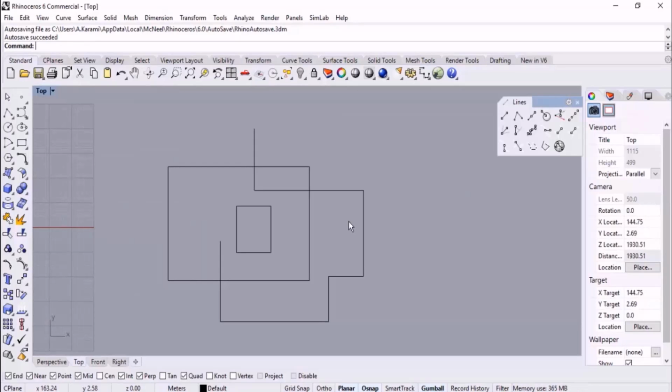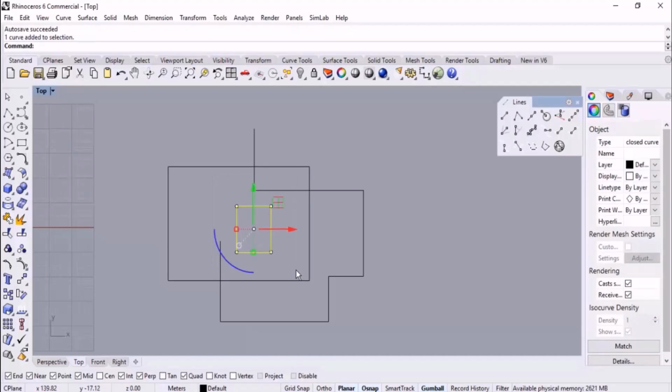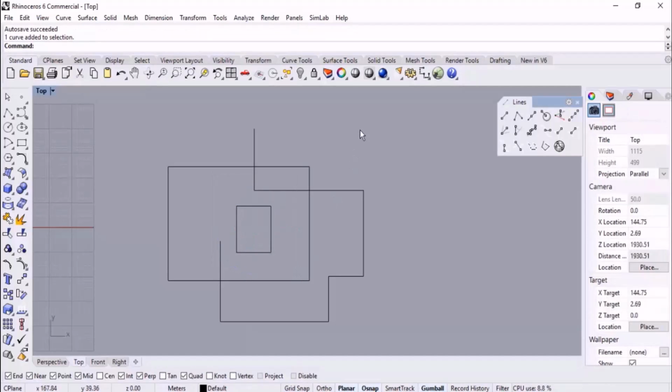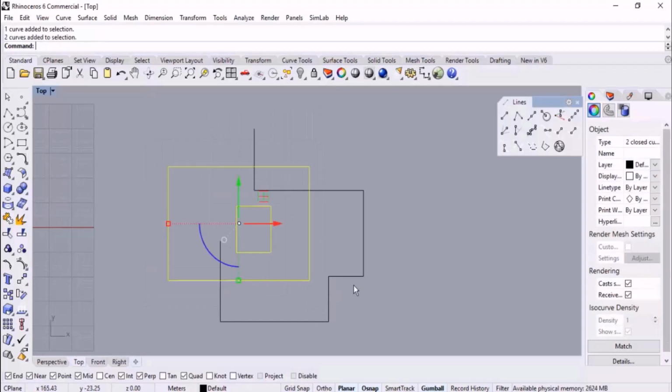Here I'm gonna tell you 3 techniques for selection, which are totally similar to AutoCAD. In the first approach, we sketch a region by click and drag from left to right, but under which condition can we select some object by click and drag from left to right? Excellent. The whole object should be covered in the region, or the window that we sketch should include the object. So in the first approach, we sketch a window by click and drag from left to right.